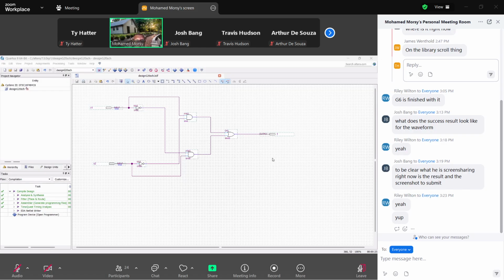Now we click on edit, set end time. We choose 4 microseconds. Then edit, we choose grid size. Click on the grid size. We use 1 microsecond for the grid. 1 micro, not nano, micro. Okay.